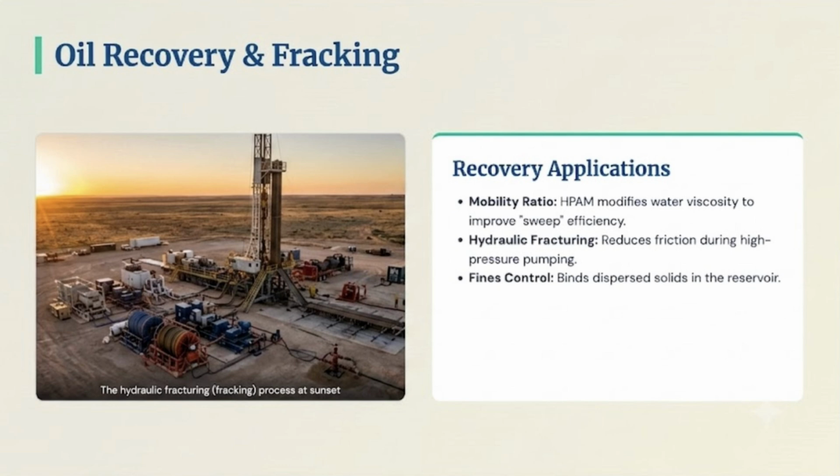Beyond the oil and gas sector, polyacrylamide improves fiber retention and drainage rates in the wet end of paper manufacturing, increases thickener throughput and overflow clarity in mining operations, and supports textile sizing. These industrial applications typically operate at modest parts per million dosages, resulting in a 5% to 20% increase in solid capture alongside significantly clearer filtrates.